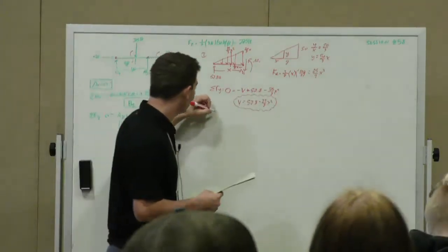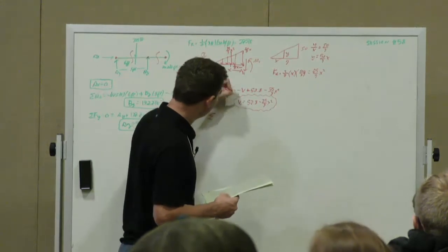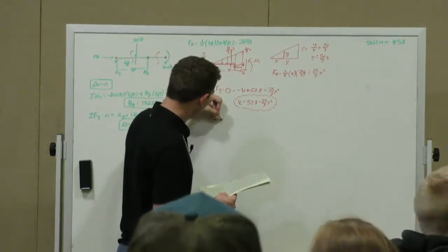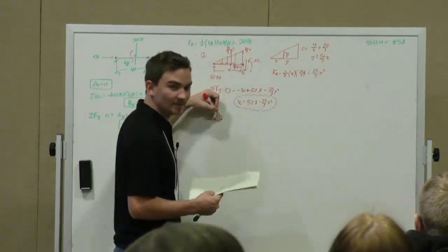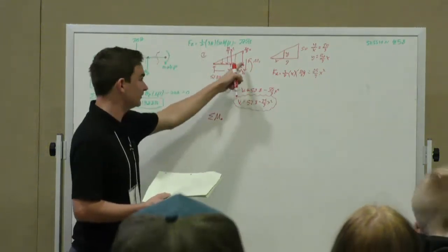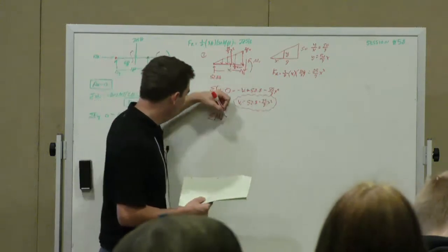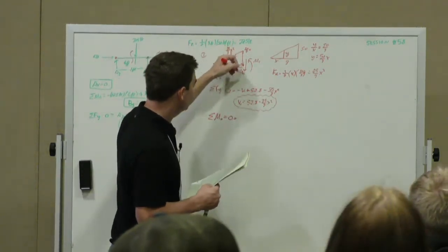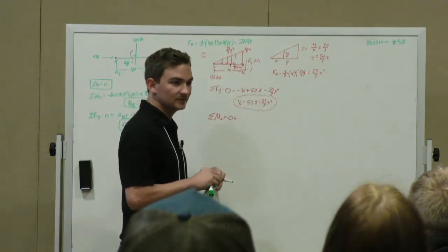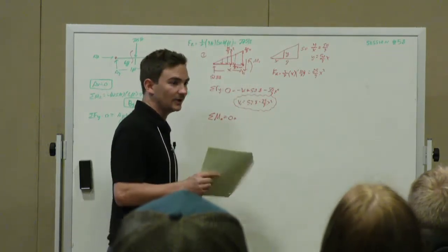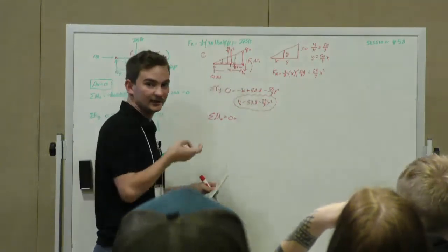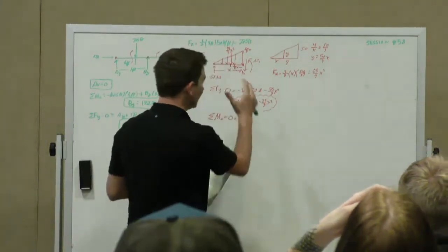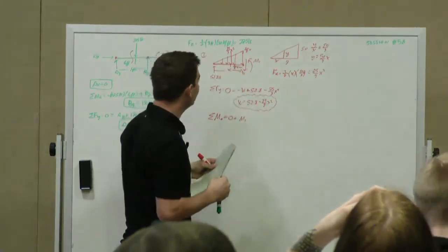So now how do we find our moment? And this is shear 1. So we could take a moment about the cut point. I'm just labeling it as m dot, which just refers to the cut for me. So this again is equal to 0. Does the shear cause a moment about the cut end? No. Since it passes through that cut right there, it doesn't cause a moment. However, we still have to include our m1, and that's positive using our right-hand rule.